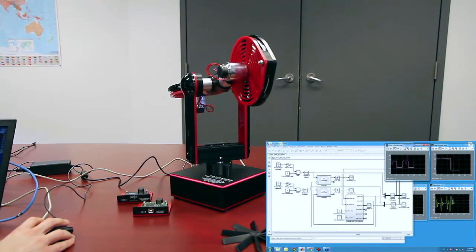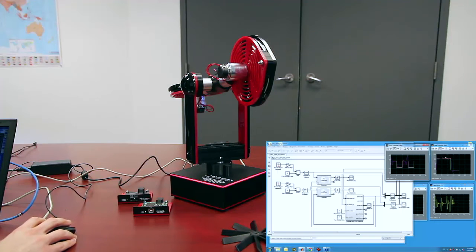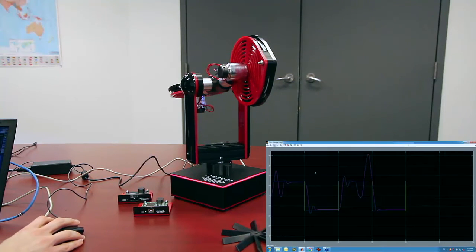So this represents the coupling in here, right? When the yaw moves, you get this huge motion in the pitch, and you should be able to see it on the screen. So here's the yaw encoder. When the pitch moves, you get these little perturbations, if you will, along the yaw, right? So the controller has to compensate for this. These are the torques that are introduced from the pitch when you control the yaw, and these are the same that are affecting the pitch when you're moving the yaw.